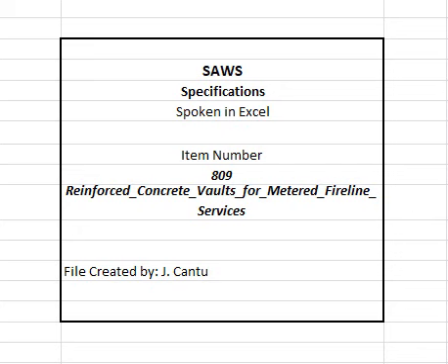7 days, respectively. 9. If 7-day or 3-day test strength, as applicable for type of cement being used, fail to meet established strength requirements, extended curing or resumed curing on those portions of structure represented by test specimens may be required. 10. When additional curing fails to produce required strength, strengthening or replacement of portions of structure which fail to develop required strength may be required by inspector, at no additional cost to SAWS.